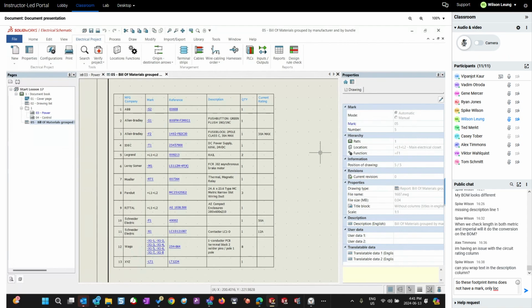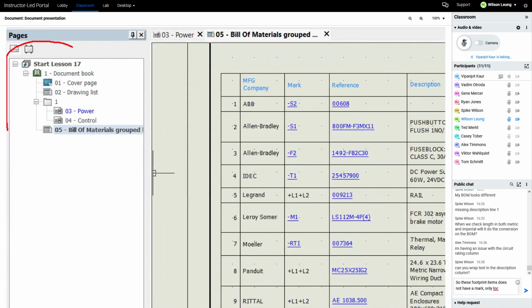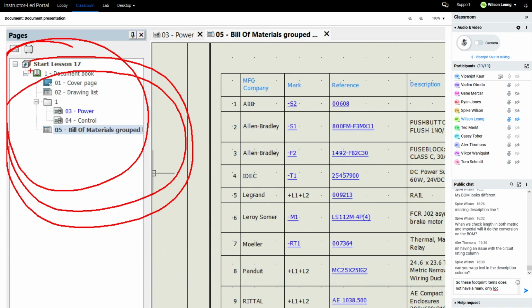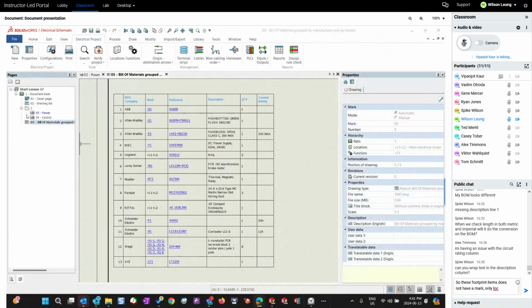I'll start checking. Tom, let me see yours. Okay, Tom. So now you can right click on that BOM list on the left, right click on that report in the document tree, in the documents tab. This is my documents tab, Tom, on the very left. Right click on this and click on the update report drawings button. It's sixth from the bottom. Update report drawings. Good job. Does it update for you? Aha, it did. So proud of you. Thanks. Look, evaluate your report now.